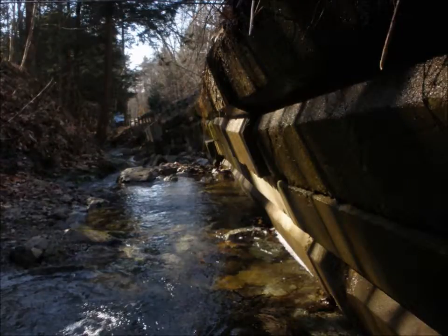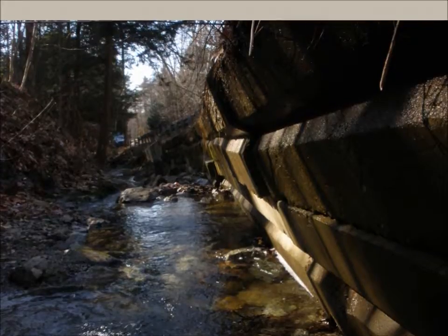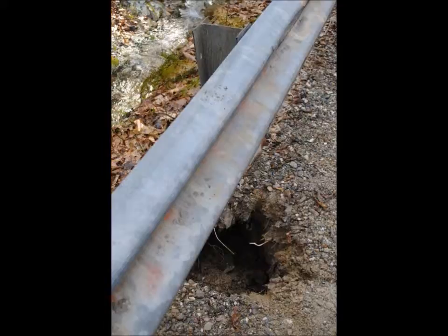The wall is beginning to overturn. This is due in part to the high water table behind the wall, which creates larger active pressures. Another reason for the overturning of the wall is that the soil behind the wall has been washed out and subsequently has been refilled and recompacted.